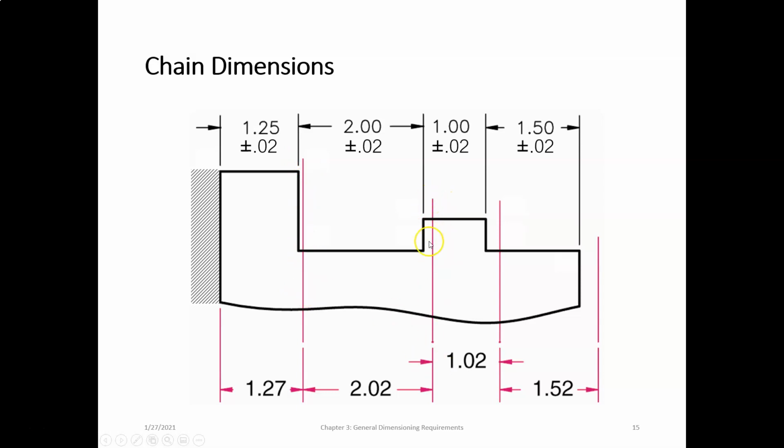So now this surface, this red line indicates where this surface would be, is again pushed 0.04 inches to the right. So we have a tolerance of 0.02 acceptable, pushing this surface to the right. The tolerance accumulation means we have 0.02 again, and then 0.02 further, and you can see it just carries on. So this surface would be out here, and then the ultimate, the total response here would be this surface gets pushed way out here.